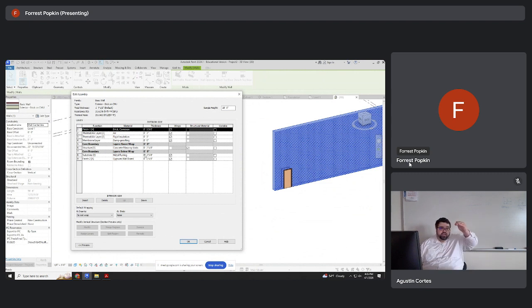So you're starting from the outside and building your way in. You start with brick, then the air layer, rigid insulation, some damp proofing, then the masonry units. You'll see here it says core boundary. This is typically used for what's doing the most weight lifting. So you could have a stud, you could have CMU block, it could be a bunch of things. Then you have the metal furring on the inside, and then of course the gypsum board that's going to be supported. So that's typically what it would look like.